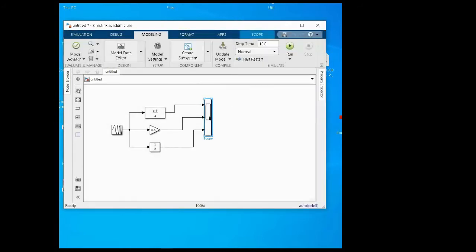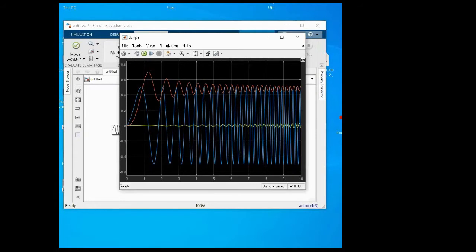And again, we will open the scope and now we can see the result. Here we can see three different signals. The first is blue color. It's our chirp signal from the low frequency to the high frequency. The red color, what do you think? Is it integration or differentiation? Differentiation. No, it's an integration, because you see with the frequency increasing, our envelope is decreasing.